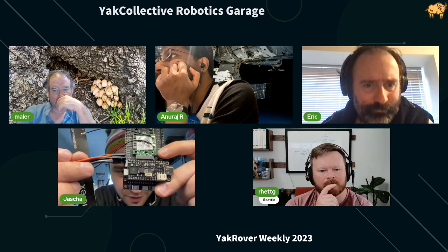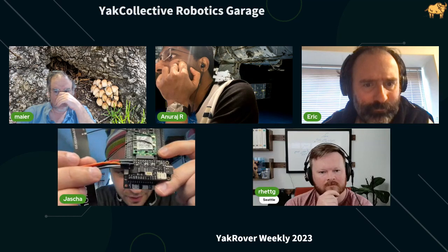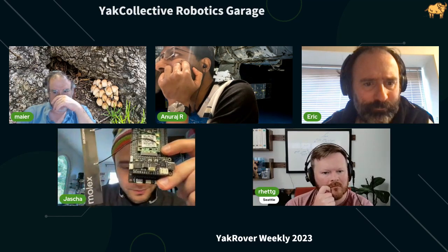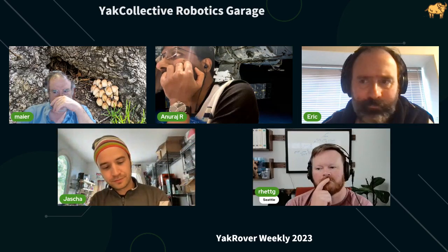It's a chip antenna plugged into the ESP instead of using the little ESP module, which is something we could do, but there really isn't, in my opinion, a strong advantage in that. The disadvantage is you don't have FCC anymore, and ideally, you don't want to make the FCC mad.